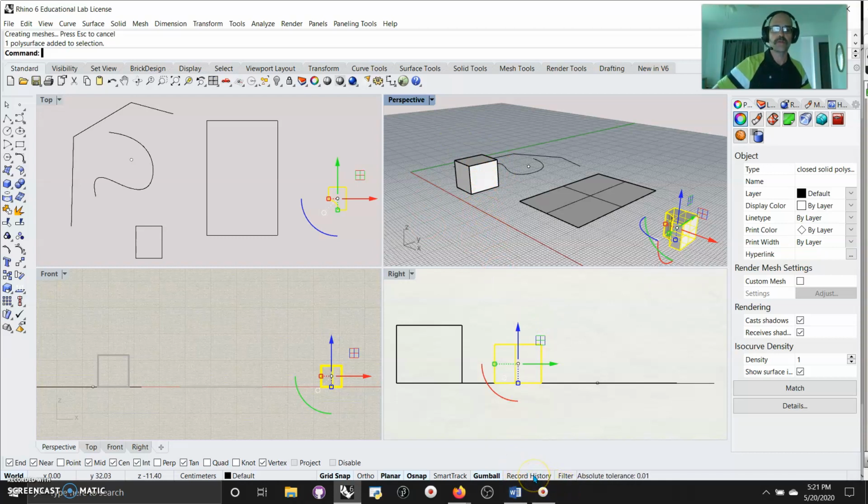You've got your record history, which we're not going to get into because I'm going to go right into Grasshopper. But I think basically you're set up here choosing what's on, what's off. You can disable this off, or I think it's Alt. Alt will just disable it temporarily, or maybe it's a different one. I don't even remember which one disables as the hotkey, but either way, you can click it off to take those off and take them on for object snaps.